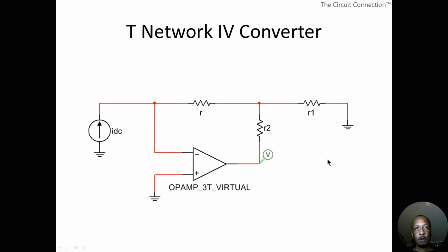When you do that, we want to come up with a functional relationship between IDC and V out. In your circuit analysis, you set up your arbitrary current flows, so I have IN going in here, which is the same as IDC, and I have this coming out here and that coming out there, and you see how I maintain the consistency. If I say that current is flowing this way in this branch of the circuit, it must be consistent throughout. So arbitrarily I just put a current here going this way and a current coming out there.